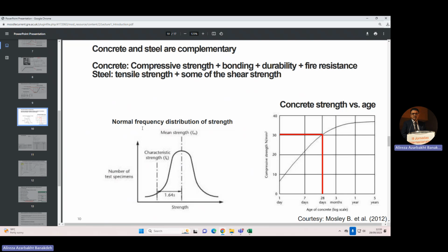But now there are some new technologies. They work like a hydraulic process. You pour concrete, and the forms move up tomorrow. Pour another one, moving up. The bottom is getting dry, you're pouring a new one. It's like going up with a hydraulic system. You don't open and close the formwork.